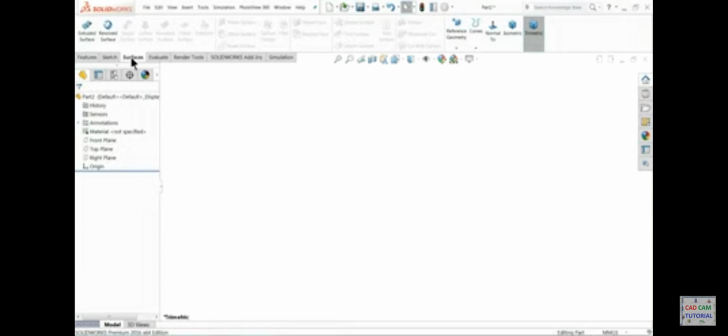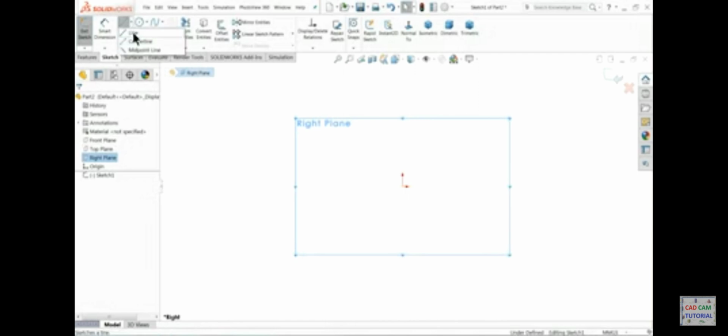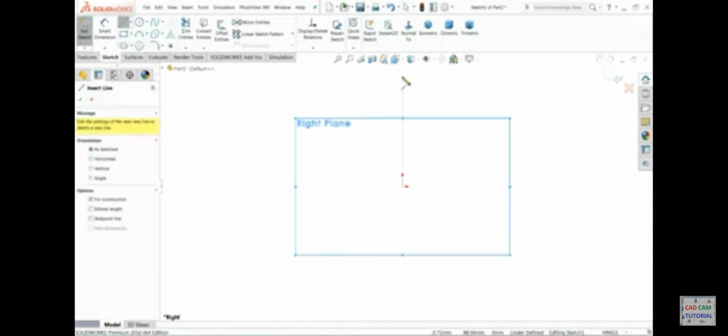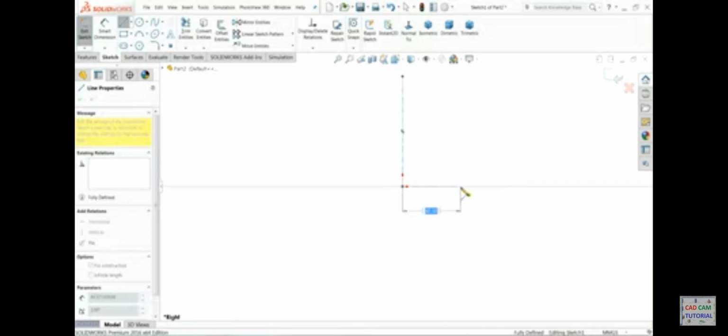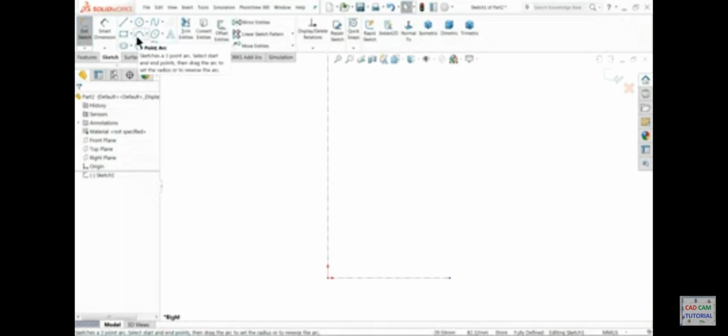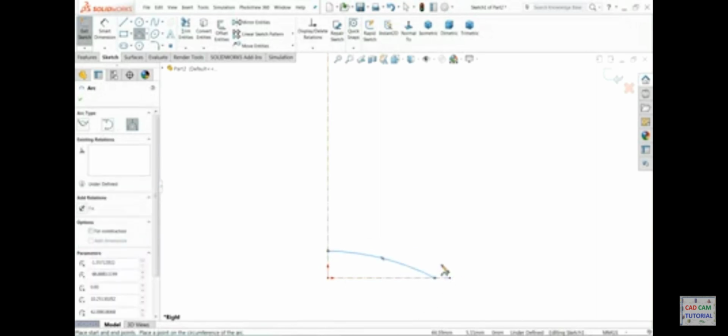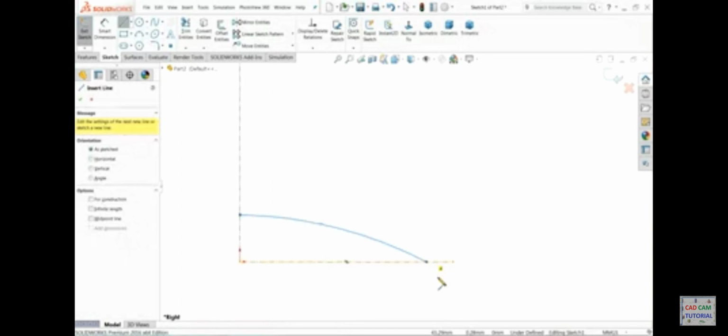So right click and choose your surface tool. So this is the surface. Either you can directly choose revolve surface or whatever plane you like. So I'll choose right plane, sketch. Okay, let me draw vertical construction line, vertical and horizontal. Tangent. Now select L command and choose line.